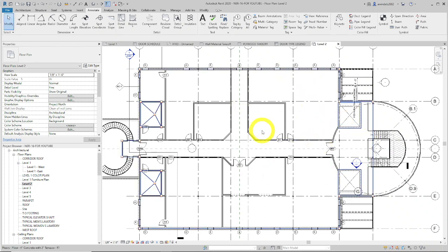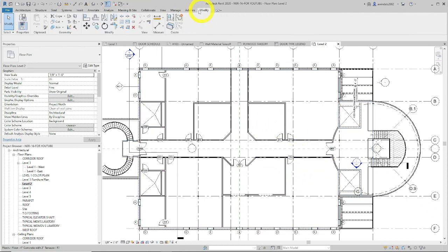The ones I didn't, copy paste to selected view with modify, copying and pasting, you might have missed some. Or you're designing a bunch of stuff on level 1 here and you copy them up to level 2 as you go along, and you don't have time to always tag everything. It helps you fill in the gaps as your design progresses. You need to add more things quickly and automated.